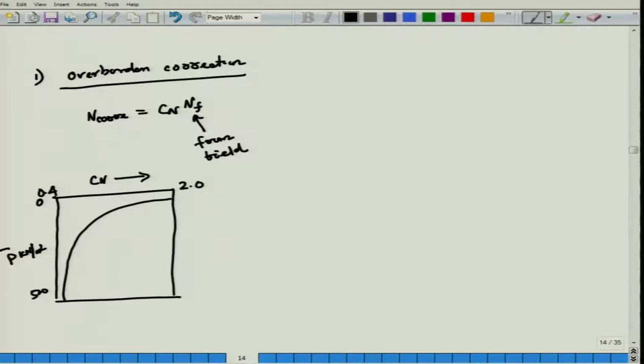So once you know a particular depth, suppose you are making a borehole, why overburden corrections? Any logic? Because what happened? Initially the ground is a level surface. You do a borehole, that means you are taking out the soil, then measuring penetration at this depth. While measuring penetration at this depth, the entire overburden has been lost. That is why this overburden correction is required.